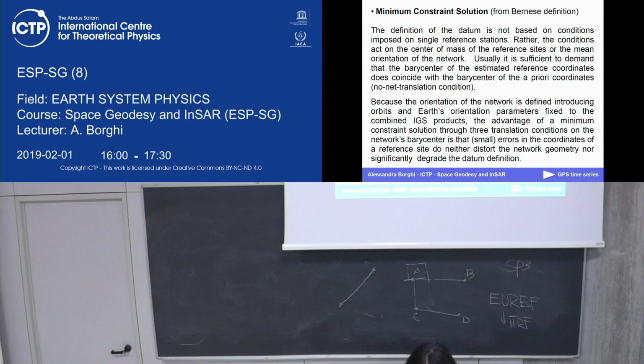But when you check this part, you don't have to apply these parameters that we are going to estimate. It's just to check if your computation is good or not. It's like a test. You say, okay, at the end of my process, day by day, I check my coordinates of the reference stations with the theoretical ones. We have an agreement. Okay, we don't see any strain residual.